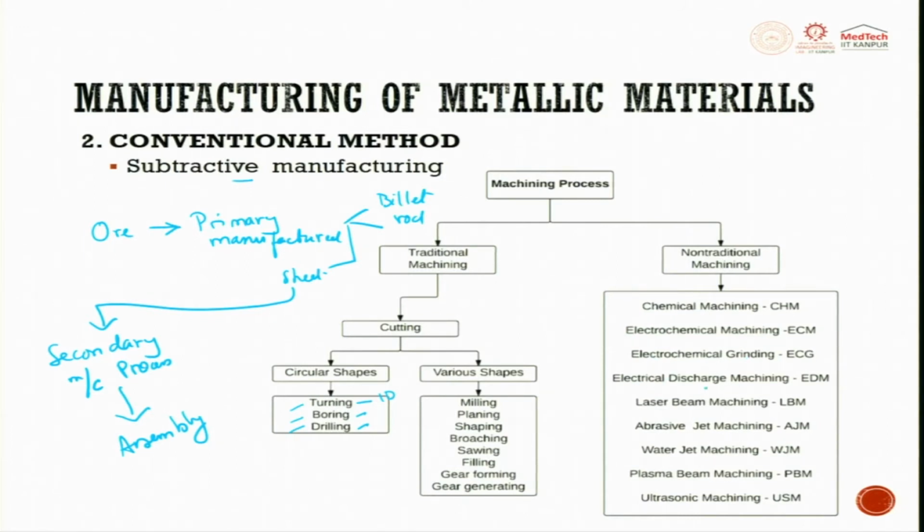We have electric discharge machining, wherein we try to create a spark, very similar to that of your laser. You will have an electrode, and between these two there will be a spark. You try to apply a high potential. This high potential tries to release electrons. An avalanche of electrons is created. They try to move along the dielectric field. They try to ionize the path, and it creates a spark for machining. So, you have this electric discharge machining. Here you can make complex parts.